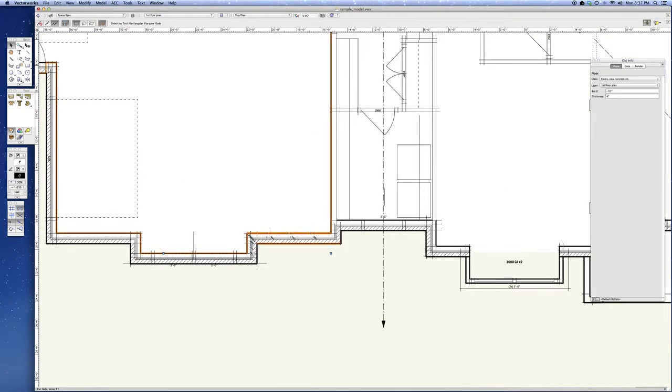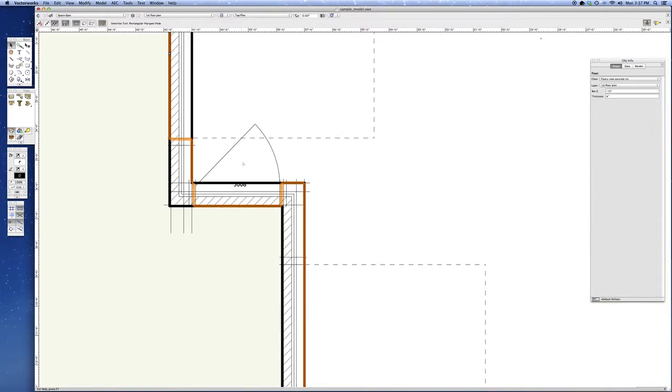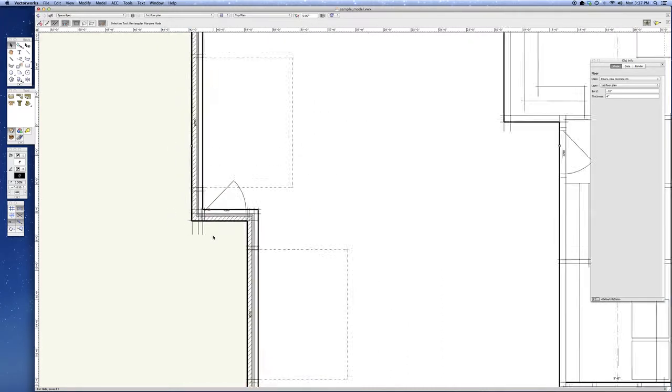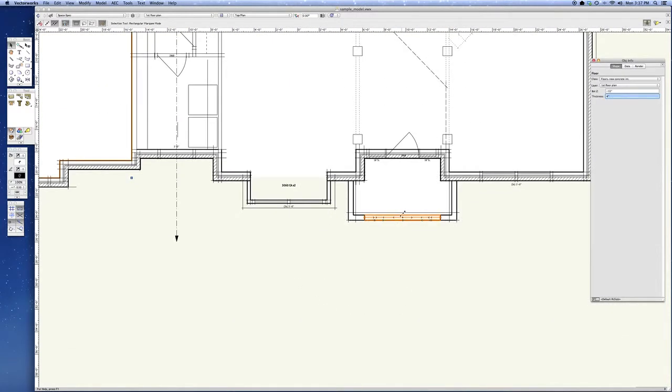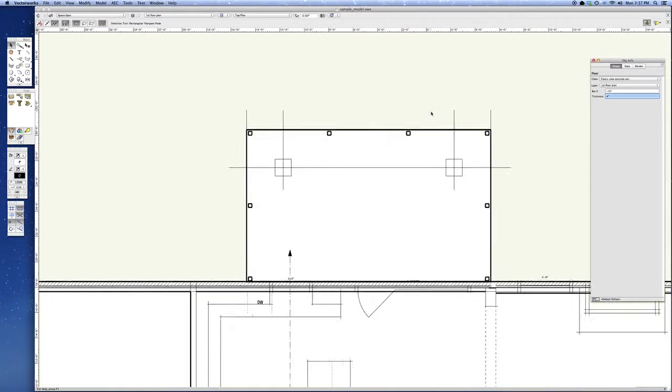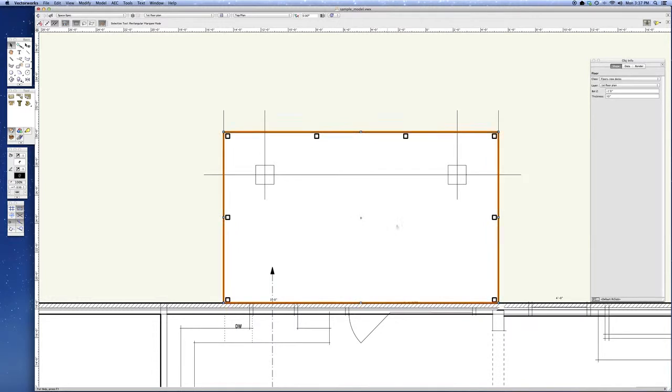That one I make to the inside of the framing, with the exception of going outside where the door thresholds are for both the man doors and the garage doors. That polygon gets made also into a floor, and it has a bottom Z of 10 inches and a thickness of 4 inches. And the class is floors new concrete interior. That differs from, say, the front porch, whose class has the same bottom Z and the same floor thickness, but that class is floors new concrete exterior. One more slab is the back porch, or the back deck, and that goes into the class floors new decks. It has a bottom Z of -12 inches and a thickness of 10 inches.